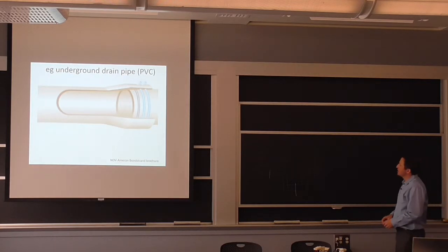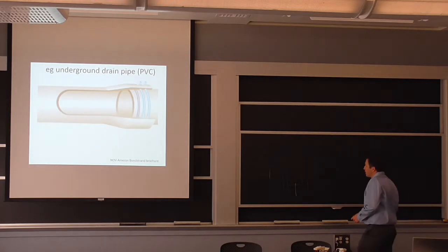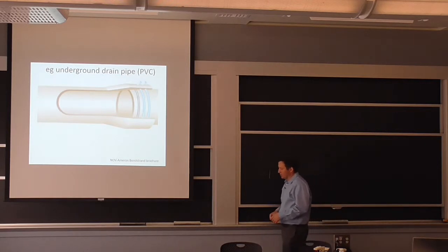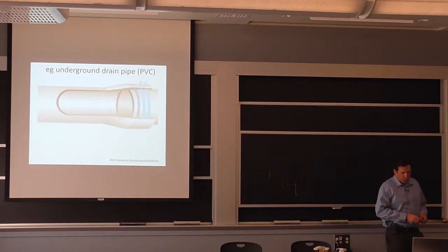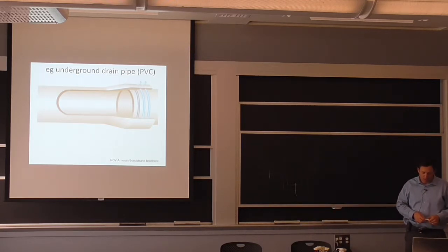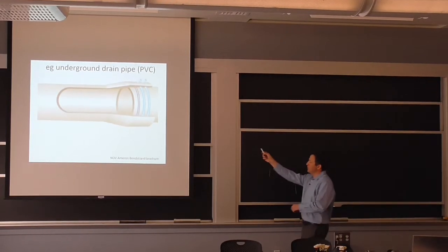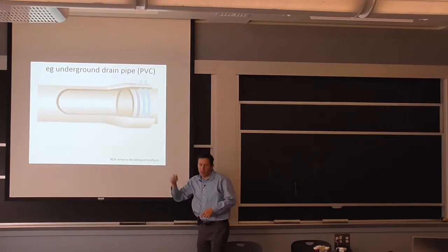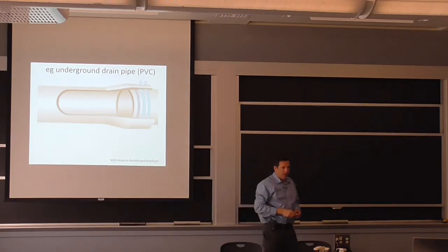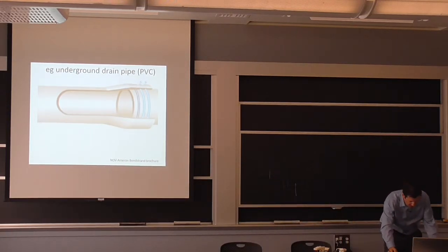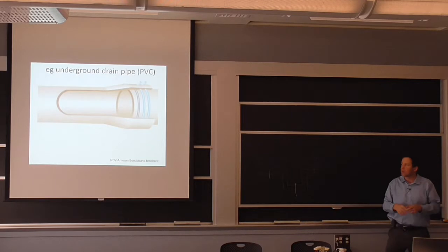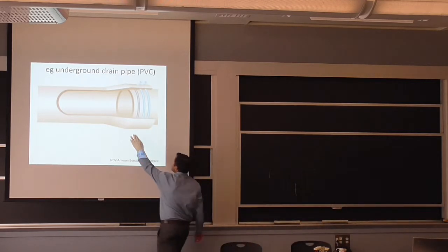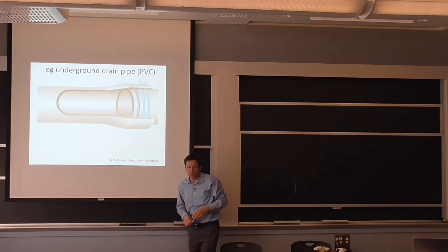The other reason I was bringing this up is we haven't talked a whole lot yet about what can happen during service, the usage factor, or say the anticipated abuse or overuse. One of these situations with this type of design is you can push the pipe too far. And if you do, then the very end of the pipe is engaging with the plastic in a cone, and you can essentially force that plastic, this surface, out, and it will crack over time.